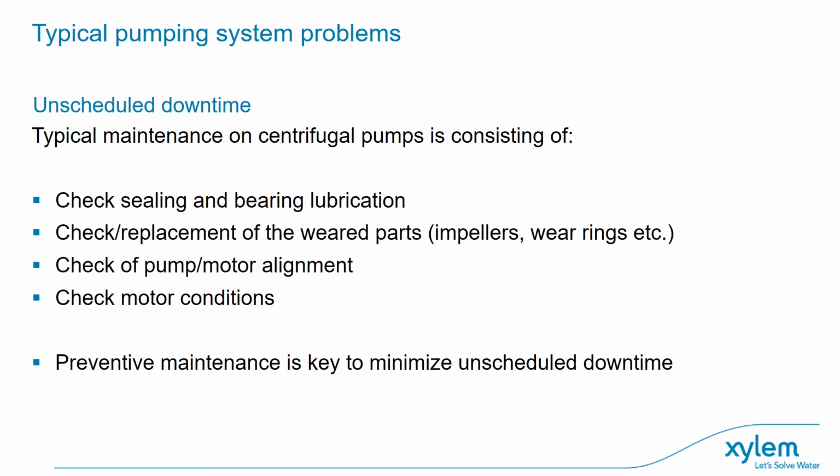Basically it must be scheduled, because if it's not done regularly, or the system design doesn't allow the pump to operate in the optimal condition, that might bring to unscheduled downtime. There are a lot of different, let's say, possible schedules that you might have in your own application, because each and every application might be different from one to the other.